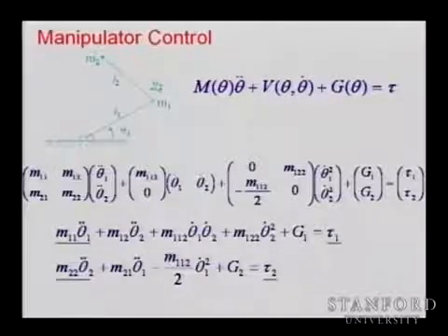We have on joint 2, what kind of forces here? Come on, you have to immediately recognize this form. What kind of forces are these? Centrifugal forces. On the top, Coriolis. So product of velocities, Coriolis, square of velocities, centrifugal, and these gravity forces.